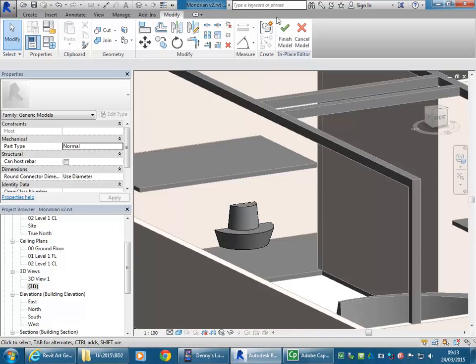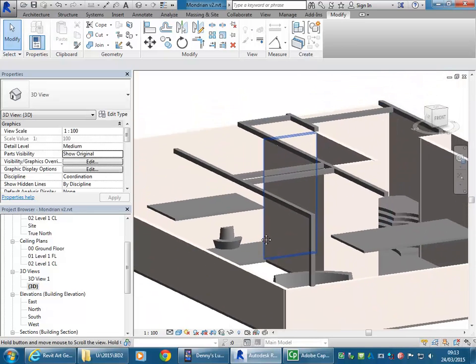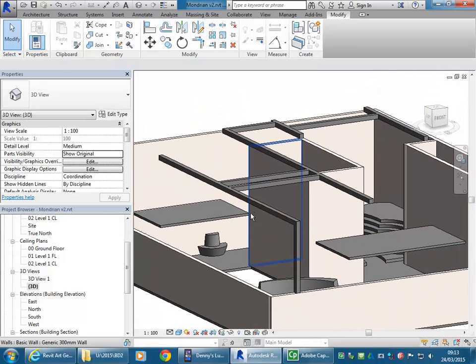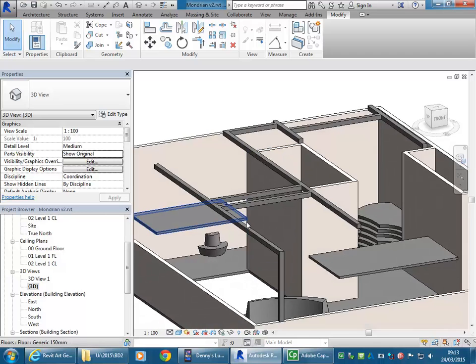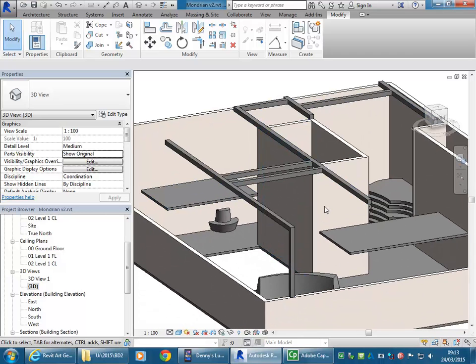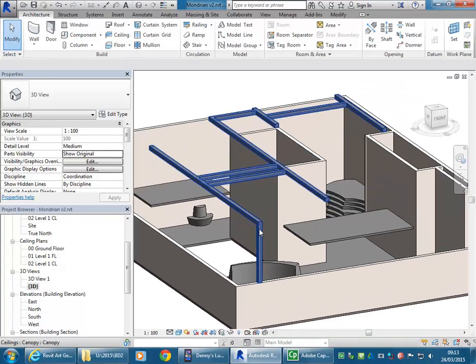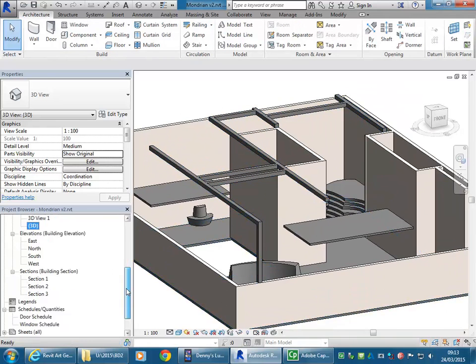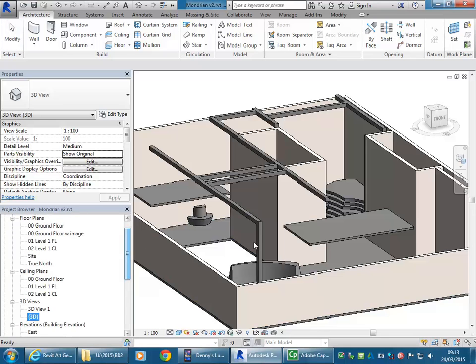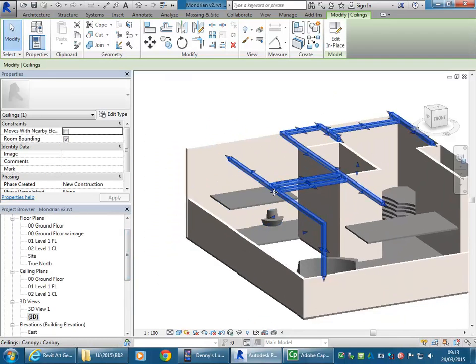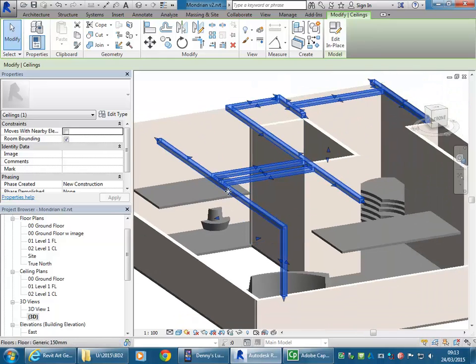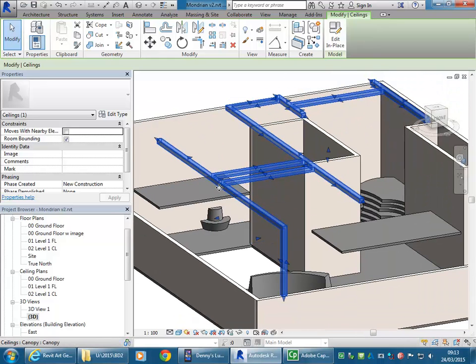So that might do it with Revolve, but essentially as you make your solids, try to think about how you can create things more easily in different planes. And so again, just maybe to remind you with the side views, I'll come back to this one, and maybe I'll just do one more edit to this solid I made before. So with that selected, to go back into it, you use edit in place.